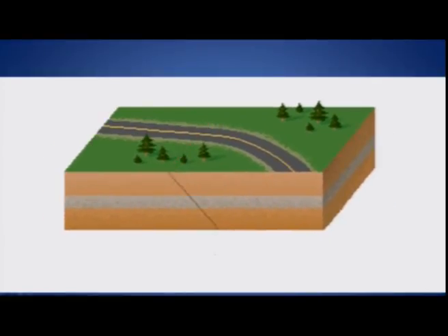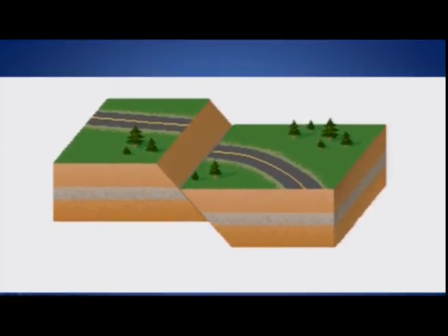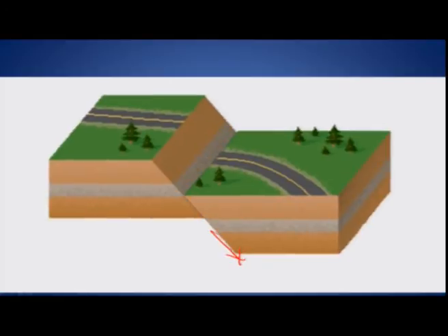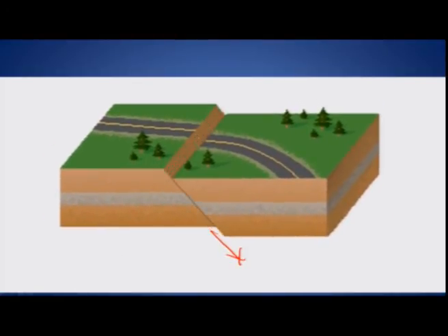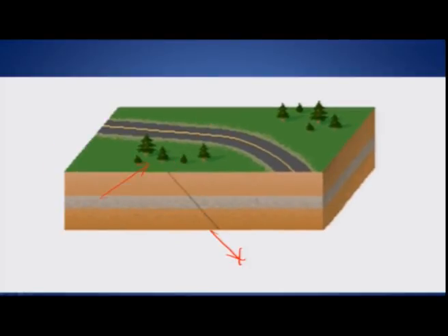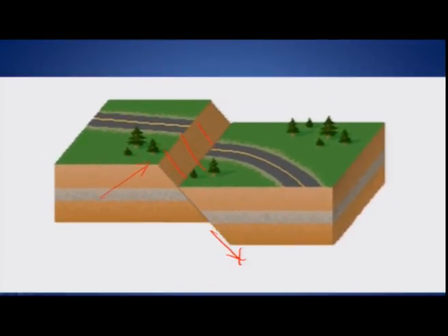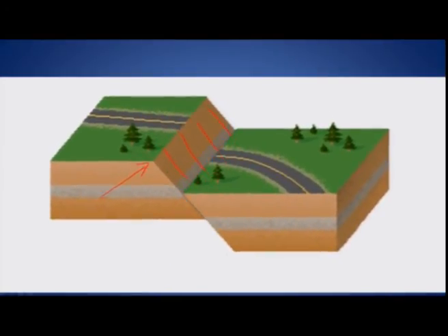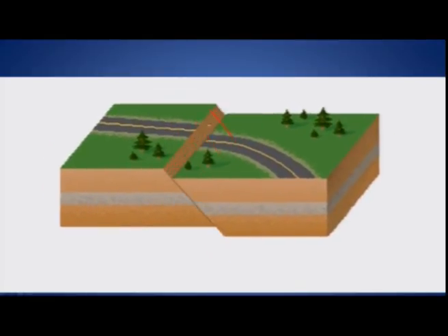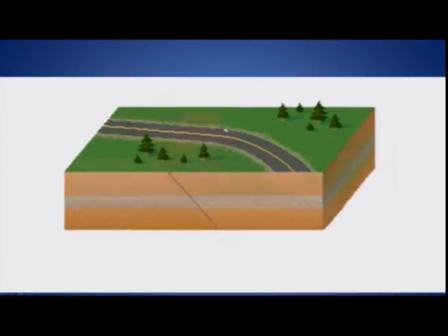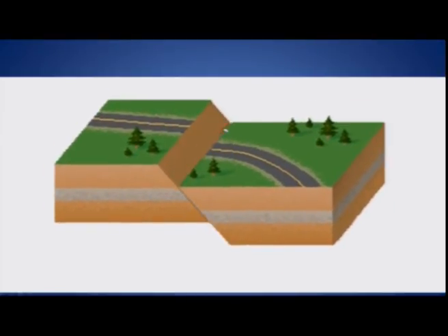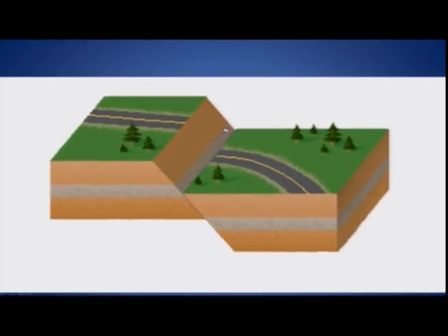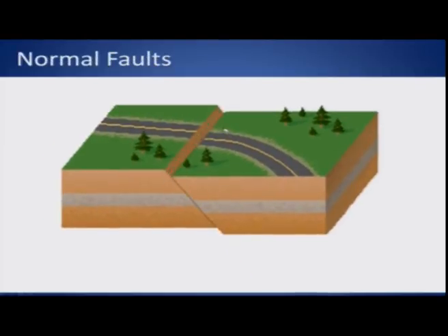Now, this one is again a fault plane, along which the movement has occurred, the block has moved down, and the strike of the fault is over here like this. And this, what you are looking at, which is coming up, is the fault scarp. Now this is a type of dip slip fault, because the movement is taking place along the dip component, and one block is moving down relative to the other. We are doing stretching, hence we term this a normal fault.